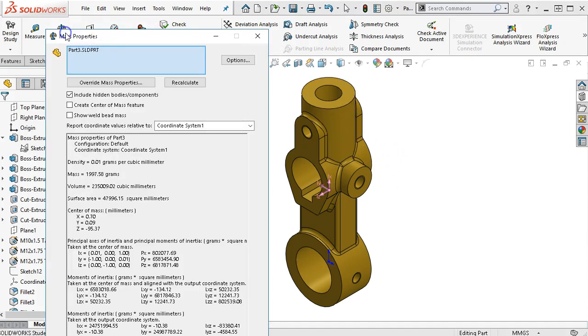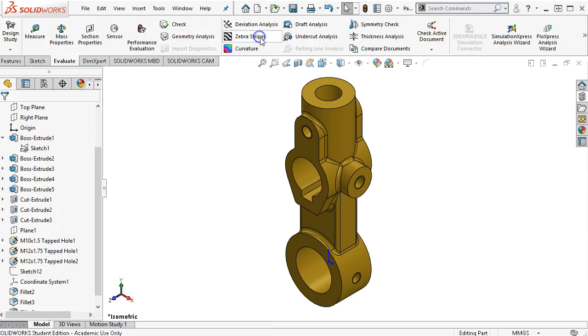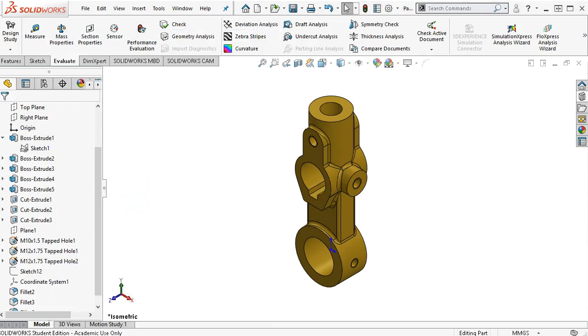All right, so one more check with the fillets in place. So we gained a gram, whatever it was, 996 to 997. Yeah, that's probably not going to be one of the changes then, because we're well within the 10% number or 5% number on our values. All right, but be able to manage the coordinate system. Don't get hung up chasing fillets if they're not well called out, and go through each of the steps, do your error checking along the way, and just focus on the part.